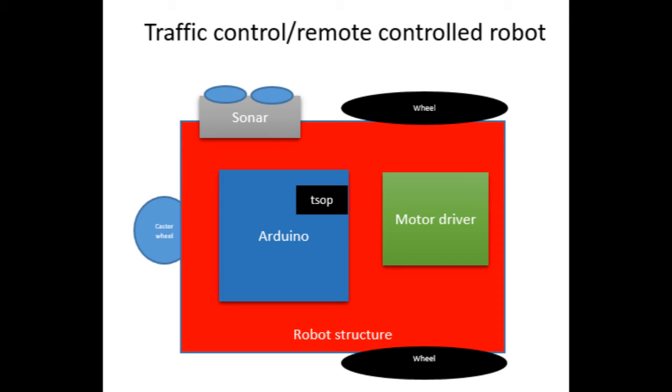Sweeping robot. This project implements a small remote controlled sweeping robot that uses a universal remote control with a TSOP1738 sensor to control the robot, which has a small broom at the front side. The remote control numbers may vary. See the LCD for each button press and find the value to insert in the if case of the code block.